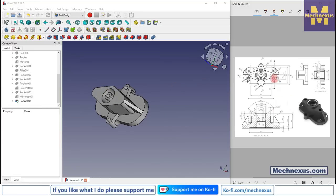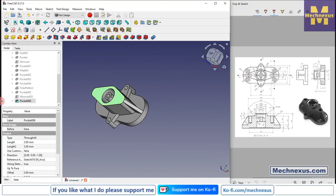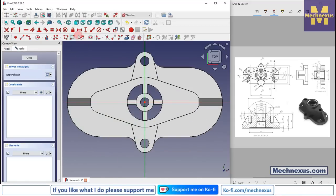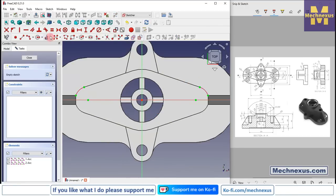Now we will create these two holes. So for this we will select this face and click on the sketch, and we will click on the project geometry and project this two arcs and create two circles, and this is of a diameter 12.